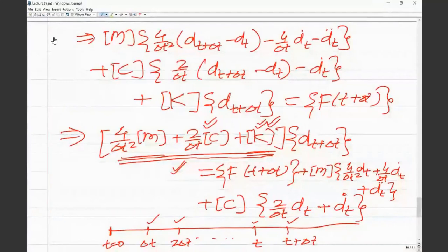So for structural dynamics, you usually use implicit techniques like Newmark's average acceleration technique, and for high deformation rate problems, which are small duration problems, you use explicit techniques like the central difference method. So it depends upon the time interval of the phenomena.